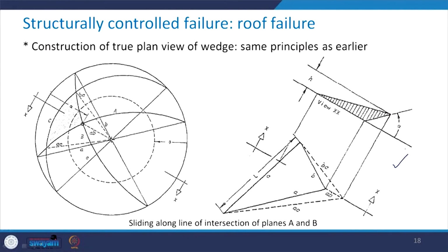So, you see that you have the great circles. This one is great circle A, this is great circle B, and this is the third great circle, C. You can obtain the strike line of these, like you see that this is for circle A. So, this is small a, this is for circle B, and this is small b, and for the circle C it is this line, and here it is represented as small c.